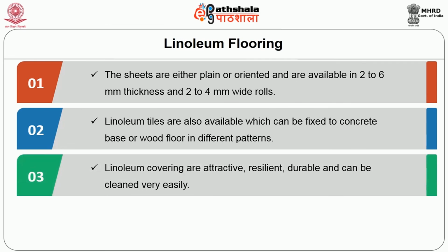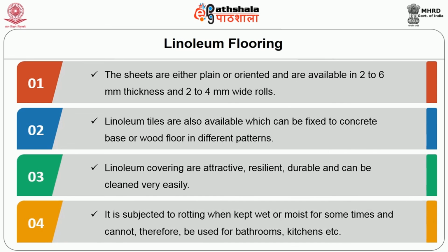Linoleum covers are attractive, resilient, durable and can be cleaned very easily. However, it is subject to rotting when kept wet or moist for some time. It cannot therefore be used for bathrooms and kitchens.